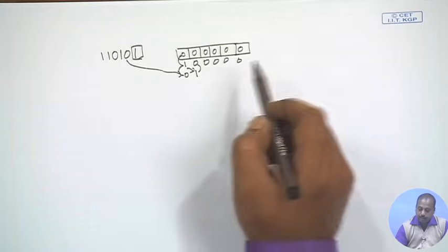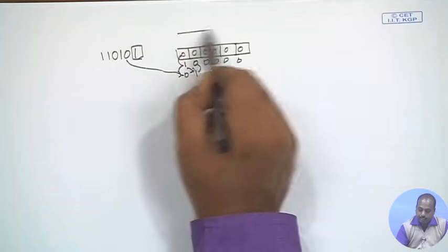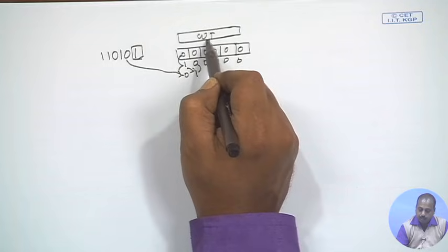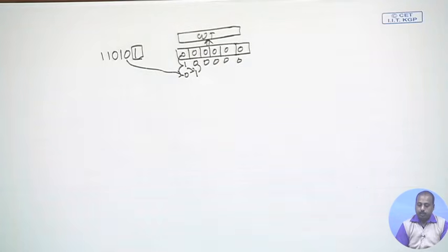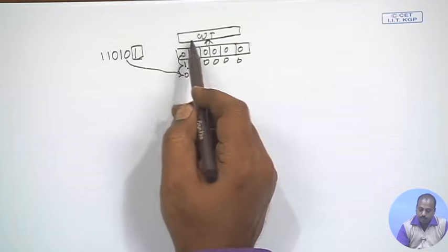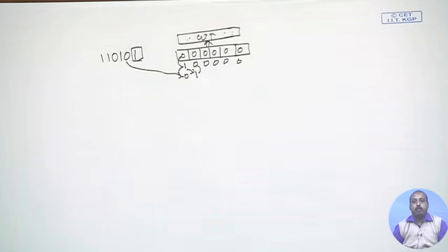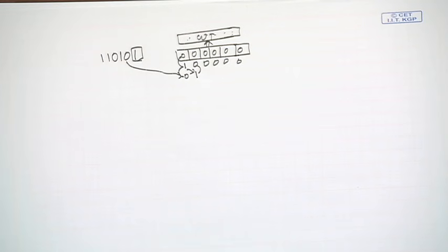Now, ideally what is required is that this scan chain output will be fed to the circuit. So, they are connected to the inputs to the circuit. For every transition that occurs, I need to compute the total number of transitions in all these gates. So, I need to do a logic simulation of this circuit for every shift that I do, which is a very cumbersome thing. A very complex computation will be required, so the overhead of computation will be very large.